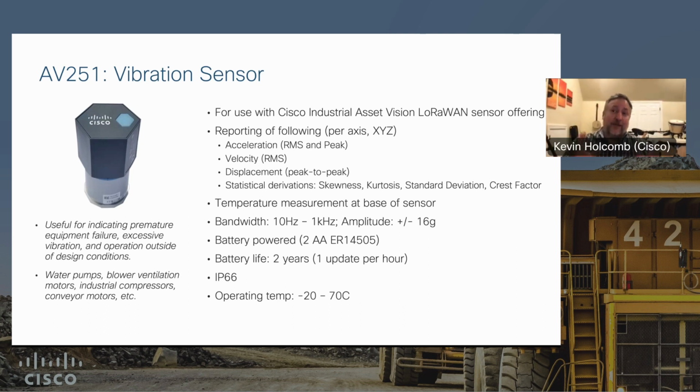So if we wake up and take 800 samples in the time domain per axis, we wouldn't be able to send all 2,400 samples over the air on LoRaWAN. So there's edge processing that happens inside this sensor and calculates all of those. Some of these are in the frequency domain, right? It does the conversions, and it reports just this summary data over LoRaWAN.